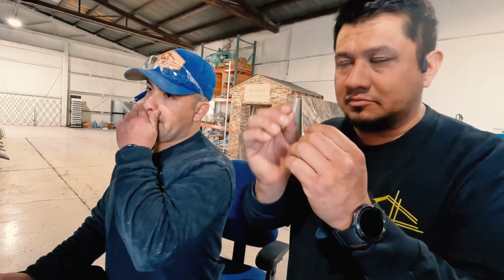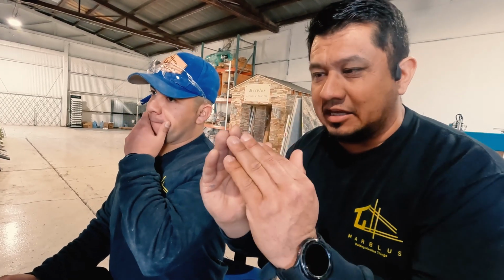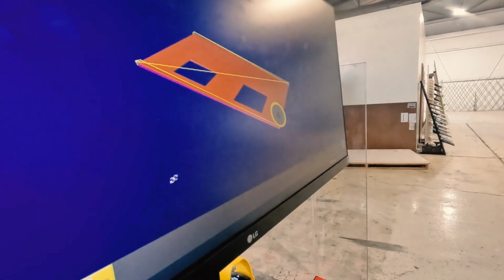Are your miters almost always at 45 degrees or different? No, we actually run it at 46 degrees. Got it. So it has a little bit more room for the glue. It's only one degree, but when you combine it, it's basically two. So it has two degrees right there. Interesting. So it's ready to send.